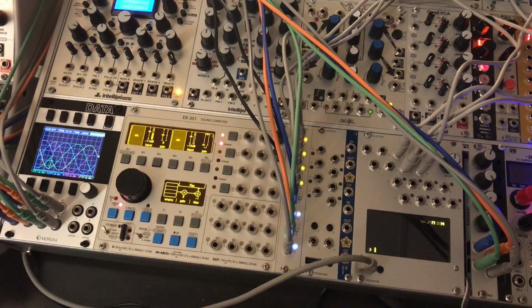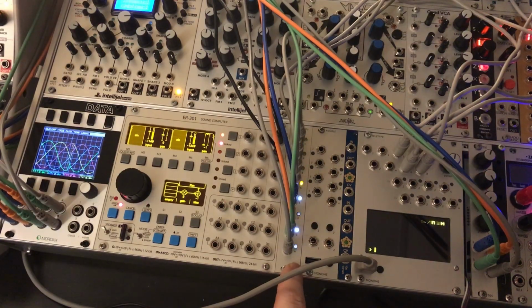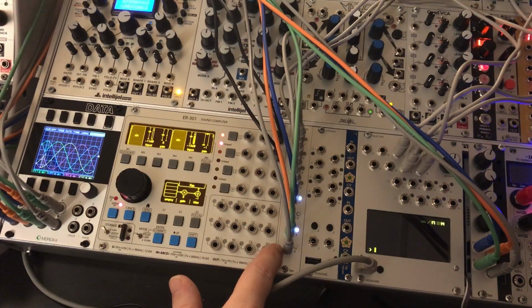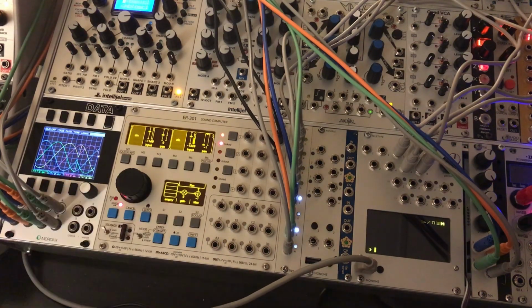So, beginning with the Teletype output expander, the TXO, we've got the 4 CV ports here. The output ports are generating a Quadrature Wavetable LFO, which you can see over here on the data. If you don't know what a Quadrature LFO is, it's essentially just an LFO that has 4 different outputs, and they put out the same signal, but the signals are out of phase by 90 degrees. So you can see that each sine wave here is a little bit offset from the other sine waves in time.